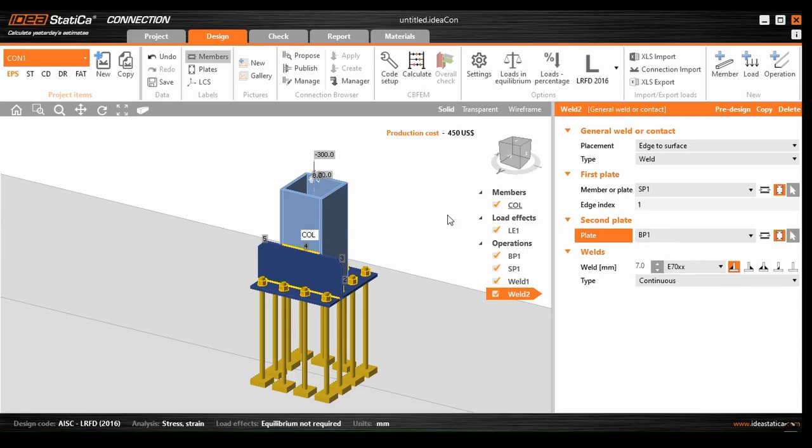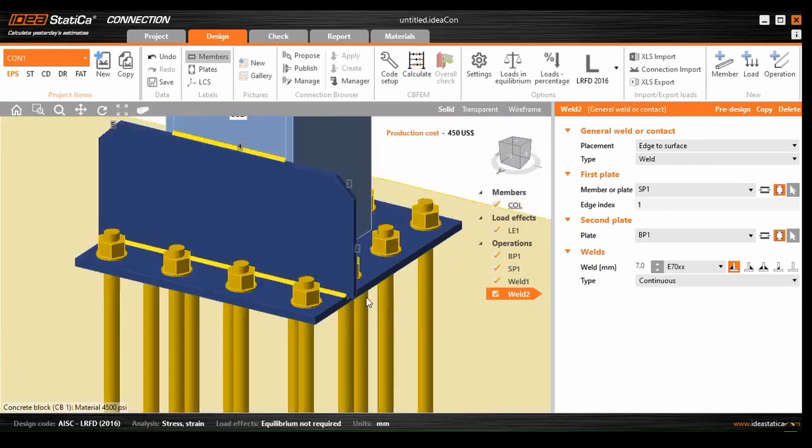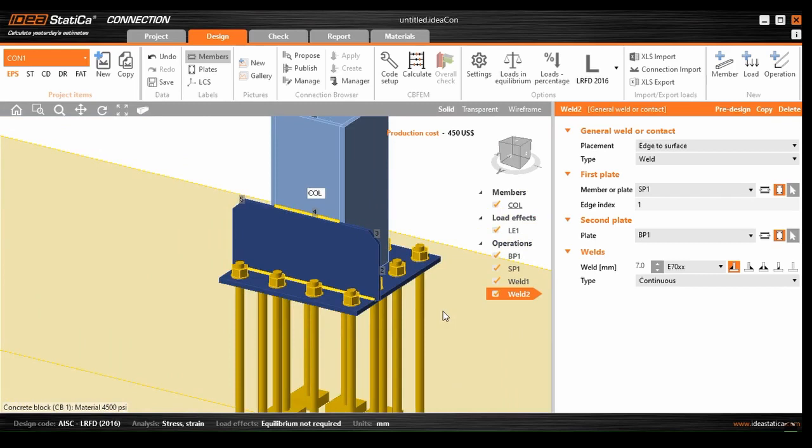And in the welding part, choose the side of the fillet welding, the right side of the fillet welding. As you can see, you can change it to this one. Okay, no, I think this one is okay. So the thickness of the weld is 7 millimeter. Likewise, weld 1. So now it's good.